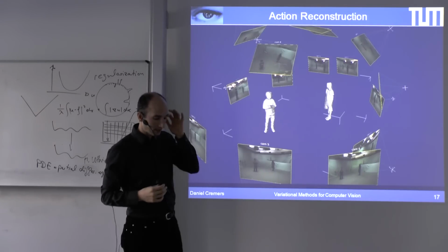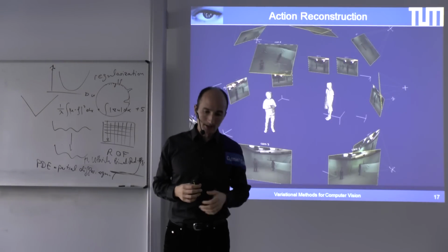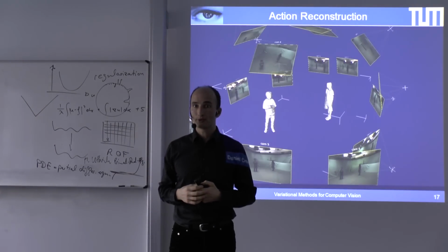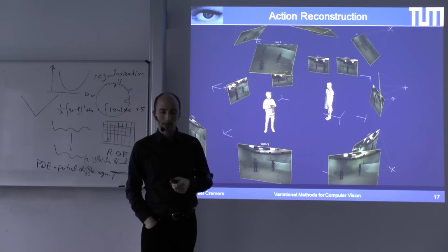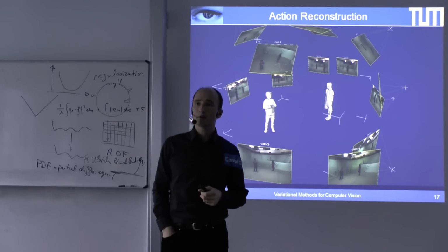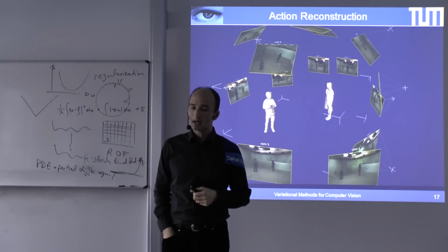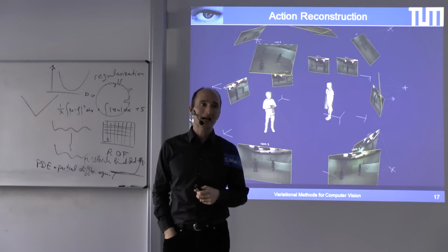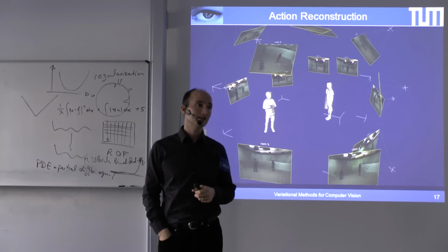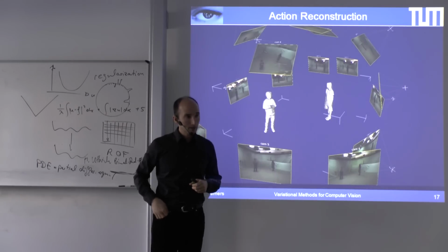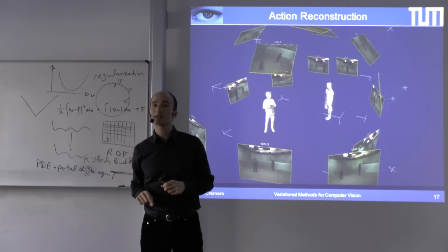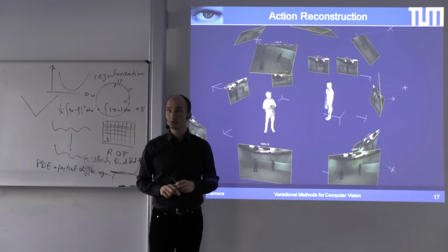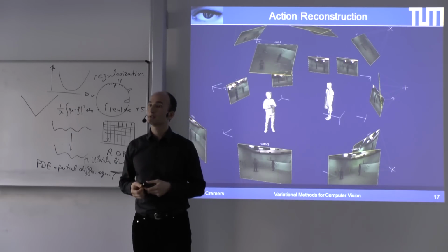Another thing, and I think this is an important aspect of image-based and camera-based approaches: if you want to recover the geometry of a structure, I believe the possibly most accurate technique nowadays is a laser scanner, because it gives you very detailed depth measurements, and you can scan the object in great detail and resolution and get a good 3D model.